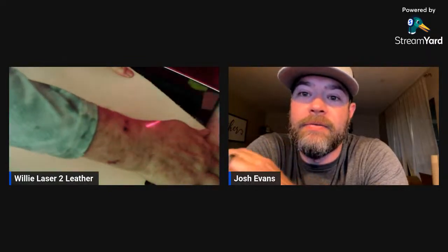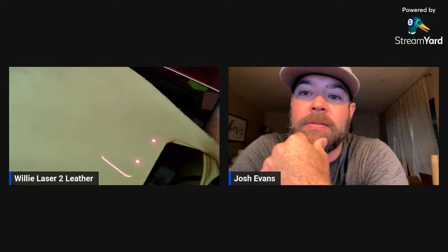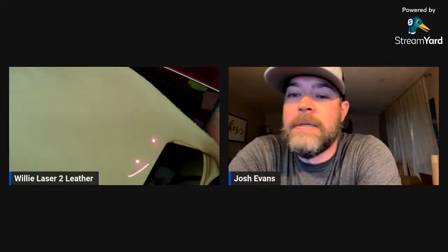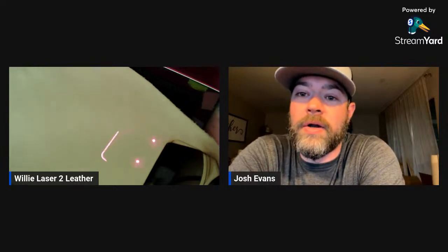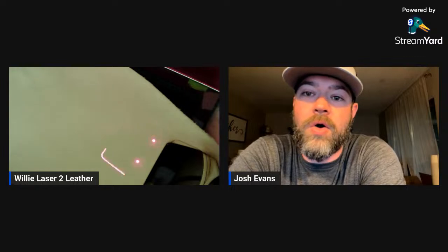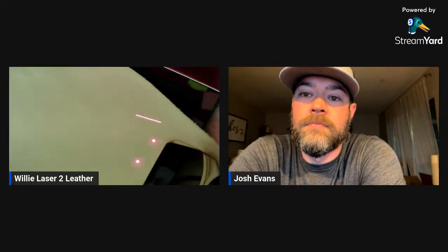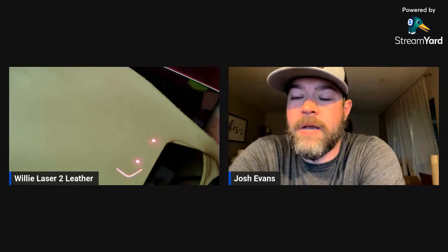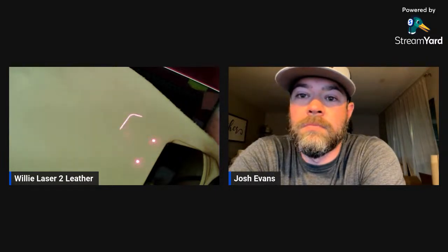Let me put some leather on here. I wouldn't mind cutting the leatherette or leather out on my Trotec, then setting up a jig and placing them on the UV and engraving them all out. I didn't know you could change the power on it, because I've only dealt with CO2 and RF lasers. It threw me off at first, not being able to adjust the power, but once you learn how to use the DPI and everything on here, you can do just about everything you could before.